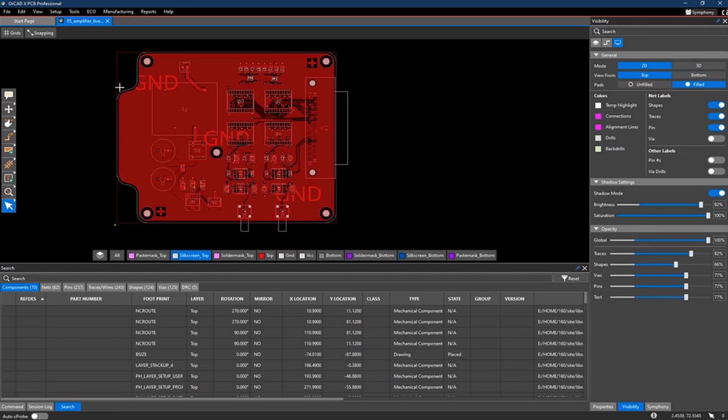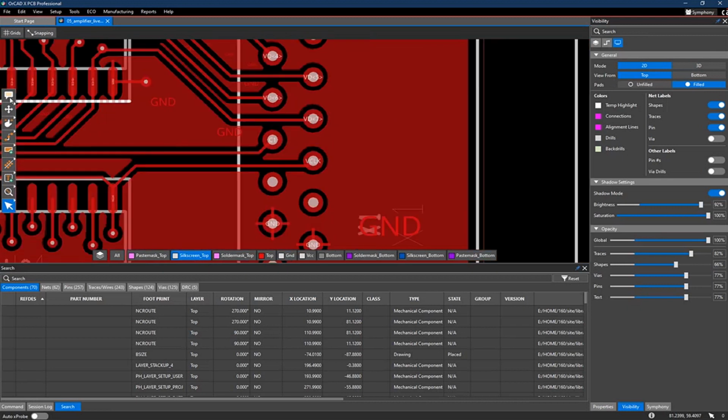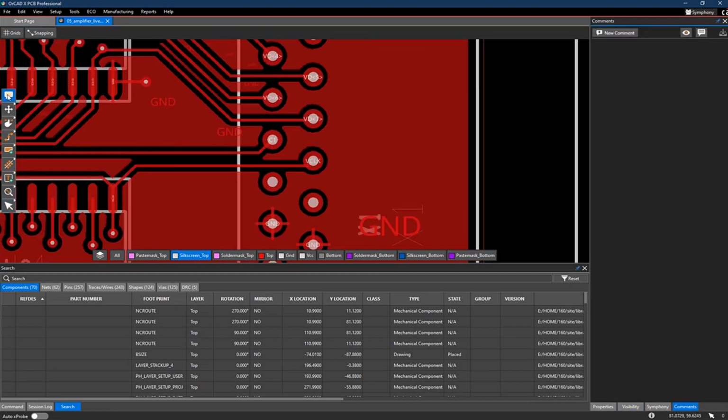First of all, let me show you the markup feature. If we want to use it, this button here is for that. Then we have the markup feature on the right side. We have this new command, and I add a command. I stay with this test point example, and add a command, add test point. For example, I can draw a rectangle like this, and then I mark up this location as a test point location for the layouter to add a test point at this location.